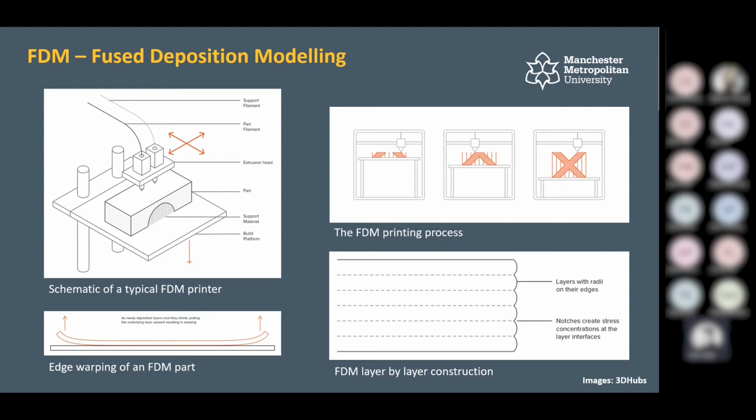So you could use spray fillers, which are quite commonly used. You can spray these in to fill in these little gaps, then you can sand them smooth to post-process, and then you can paint them, do whatever you want with them. Or you just want to sand it flat to begin with. Again, something to consider.